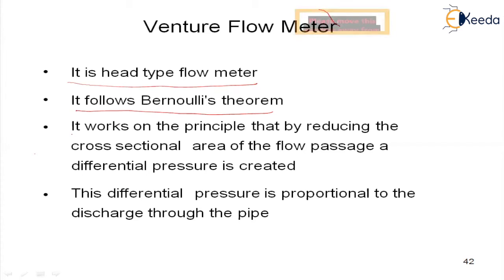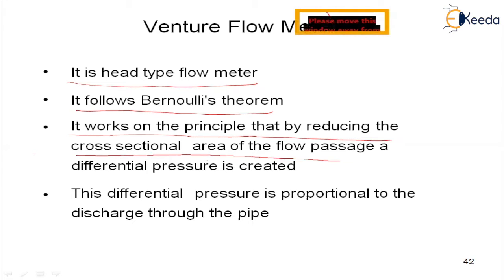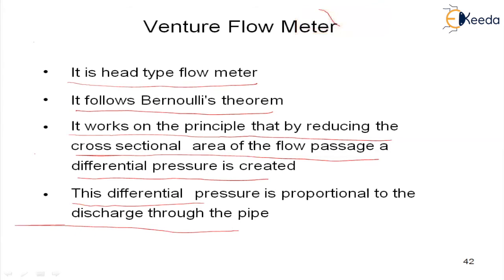Now, very important, on which principle does it act? It works on the principle that by reducing the cross-sectional area of the flow passage, a differential pressure head is created. That I'm going to show you in a detailed manner, my dear students. This differential pressure is proportional to the discharge through the pipe, my dear students. How these things work, I am going to explain in a detailed manner.